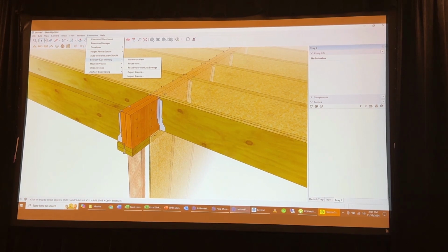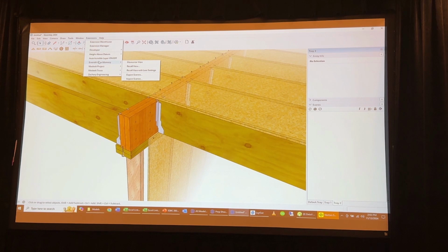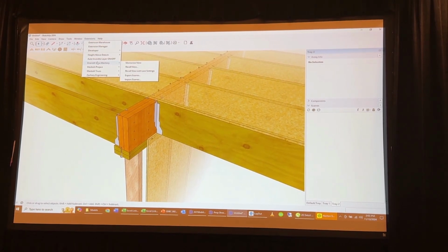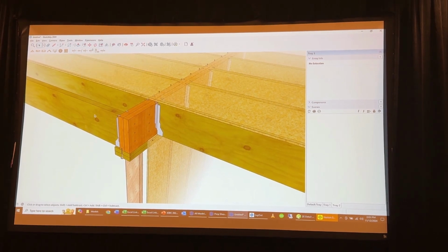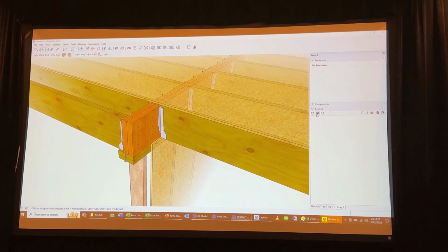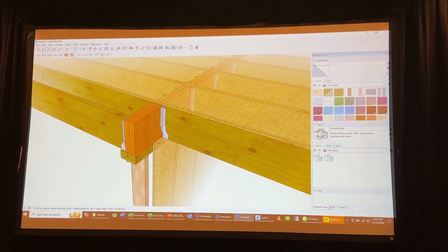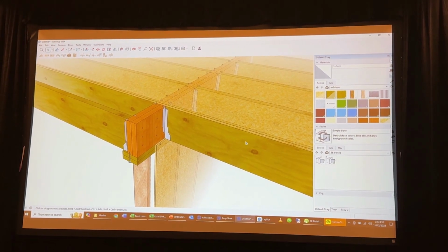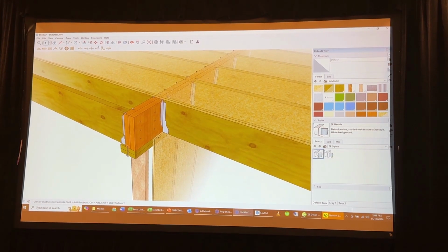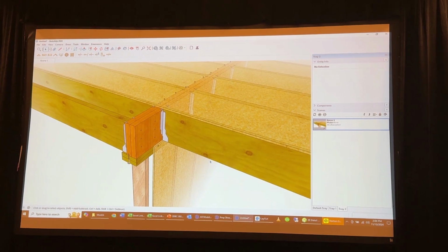You said, why were you creating a custom detail model if you're only changing a callout? Well, you wouldn't. If you're only changing a callout, you wouldn't, right? But if you make this one a different style, it freaks out, even though it's on the same style. The style is correct, but the style name is not when it brings it in. So I just go to our custom detail style, and then when I add the scene, it's good, right?